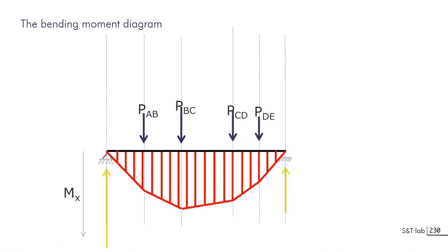The fact is that you have to write an equilibrium equation for each of the intervals between two forces. It gives you one equation, two equations, three equations, four and five equations. And you have to write this equilibrium each time you want to have the direction of these forces. And this force, as we can already see, is very close to a funicular polygon. So let's move on.